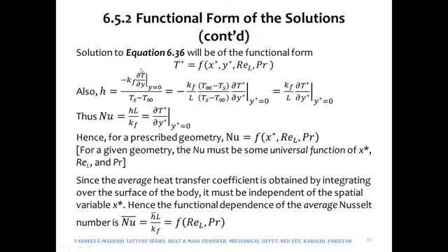And if you recall, where did we get this expression from? In fact, we have discussed this expression twice, once while we were on chapter number 1, and then again at the beginning of this chapter. So what does it say? It says that the heat transferred via conduction from the surface to the first layer would be via pure conduction, so it would be minus kf dT by dy, and then it will be transferred to the subsequent layers via convection.